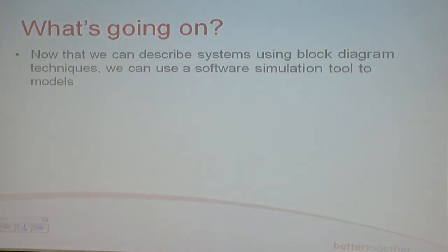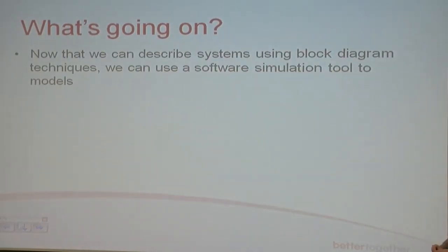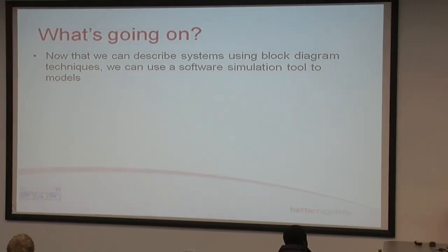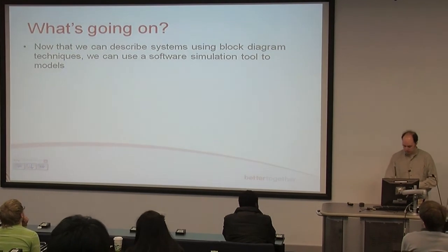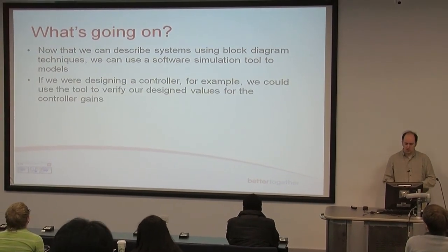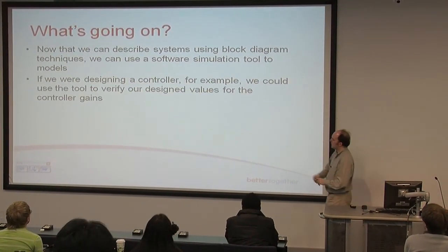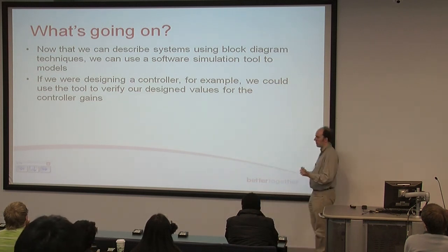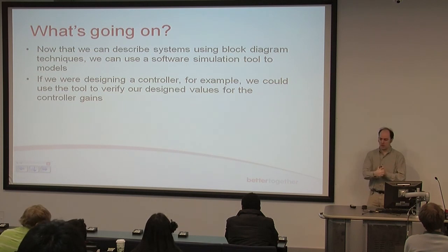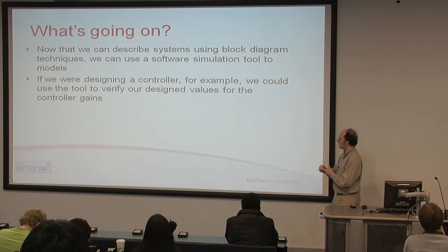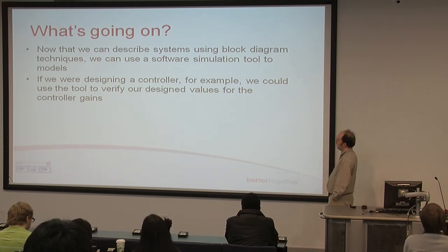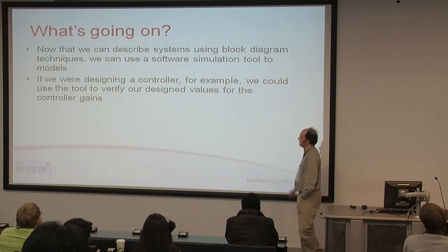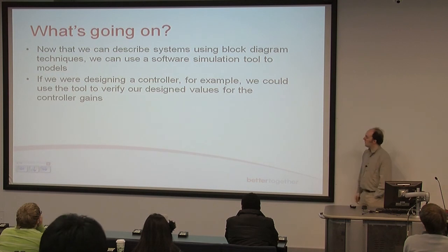What's going on? Well, now that we can describe systems using block diagram techniques, we can use software to simulate our block diagrams. Okay. If we're designing a controller, for example, we could use the tool to verify our values for, let's say we're using a PID control. We can verify our proportional gain, our integral gain, and our derivative gain by looking at the output, before you actually implement such a system in hardware.